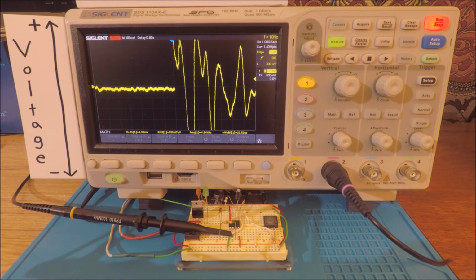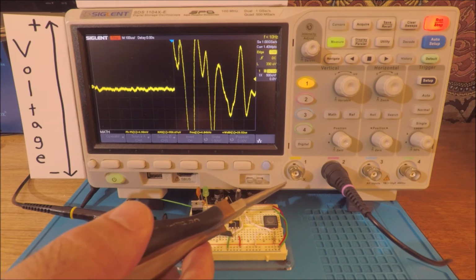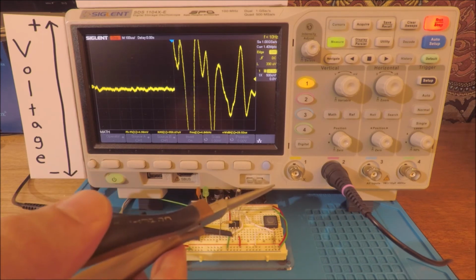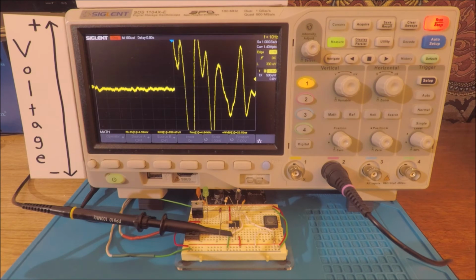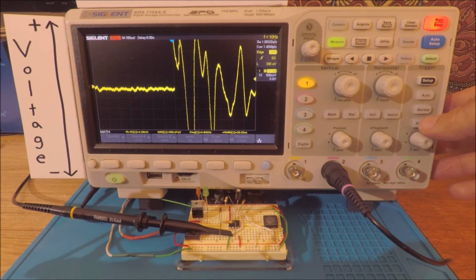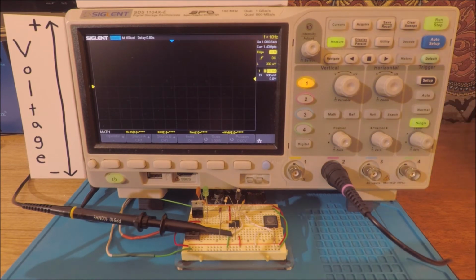We applied some stress to the input jack, the BNC jack right here, and that stress induced a voltage which exceeded the trigger threshold. And now we can see that one-shot trigger. So this is recorded in time, and we're just looking at a static picture of that one transient event. We can reset the trigger again, and we can do it one more time.